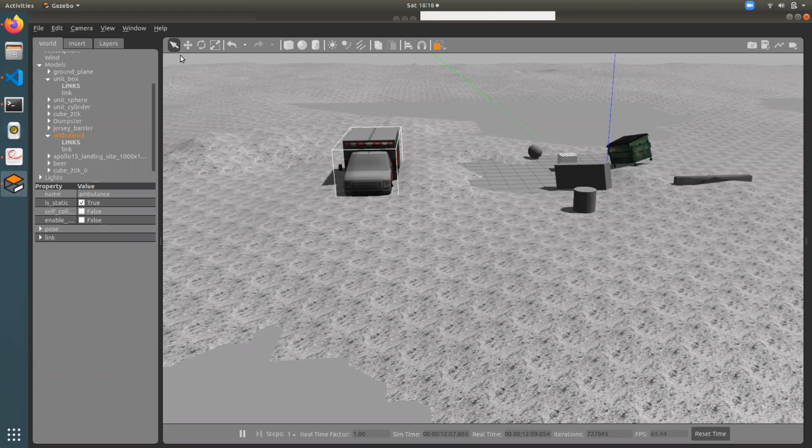There are Gazebo topics as well. So if the robot has a specific Gazebo URDF file, we'll come to that in a bit, it will capture those commands and act accordingly. If this guy has a URDF file and has a driver supporting the ROS bridge, like listening to the ROS bridge, then this guy can move as well. And if this guy doesn't have it, and if you can create something like that, then you can move this as well. Like we can test it in a dynamic environment.